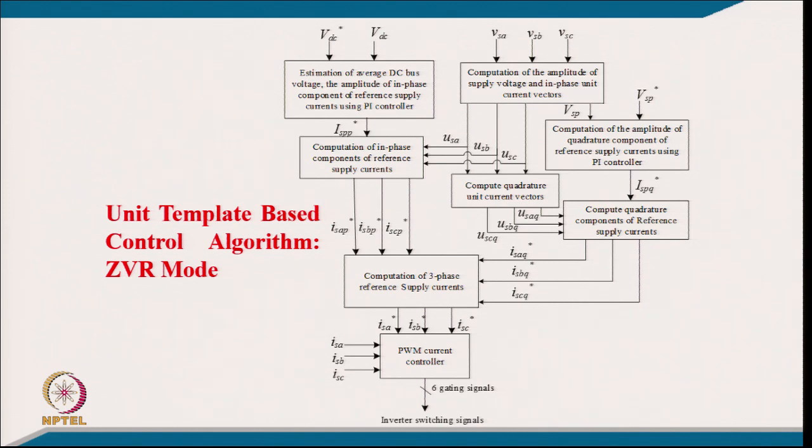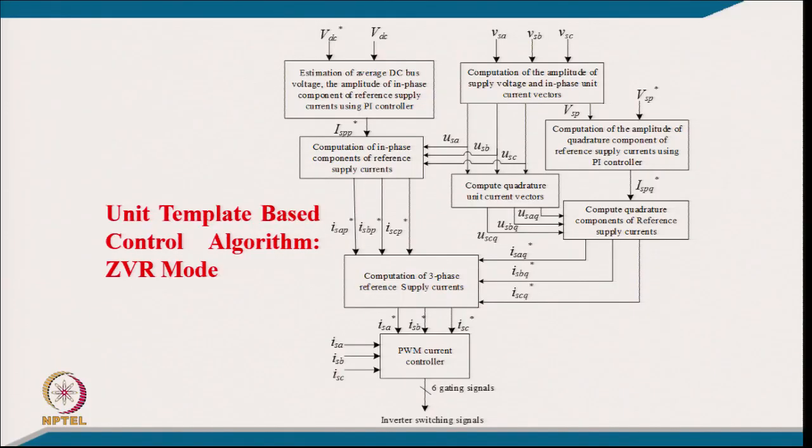But you can understand that for voltage regulation we have another component, because the load voltage can be maintained constant, equal to the value you require, may be equal to the supply voltage, when you really require a reactive component. You use a lot of compensators in distribution systems, like capacitor panels, for elevating or regulating the voltage. Here also, even if it is a normal case like inductive load or resistive load, you have to put a little capacitive current also to regulate the voltage and take care of the drop in the source impedance. Of course, if the load is already inductive and the voltage is going up, then it may be an inductive current; otherwise mostly it is a capacitive current.